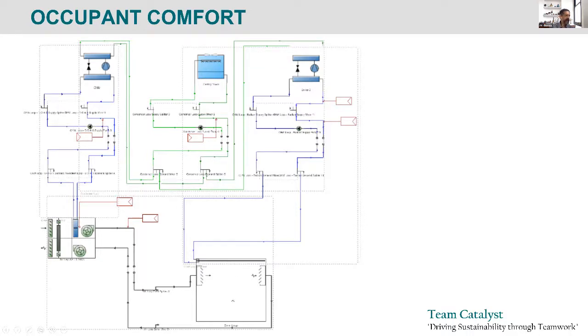And the way this is set up, it's quite a simple setup. I've got one chilled water loop that is feeding the cooling coil inside the dedicated outside air system. And I've got a separate chiller here, which is feeding the chilled ceiling. And the reason is, of course, if you read up literature on radiant systems, you'll find that the radiant systems need to be given water at a much higher temperature than the outside air system. The outside air system needs to be able to dehumidify, so it'll probably need the cooling coil to be at 6 degrees centigrade. That's the way that you might be able to dehumidify, okay?